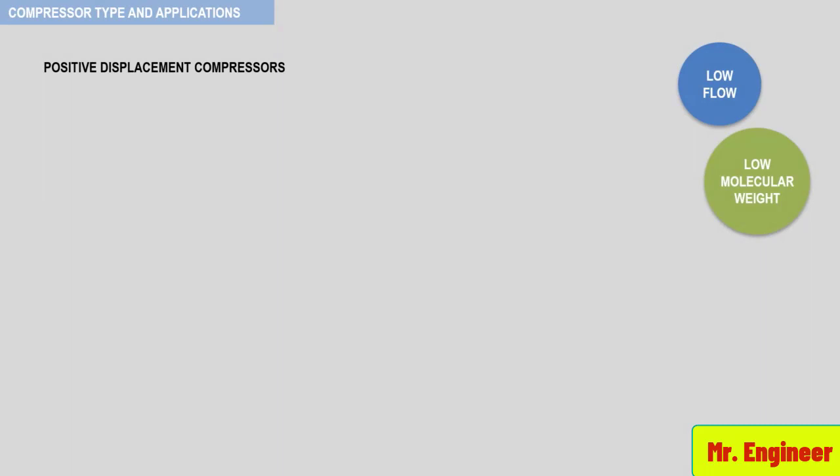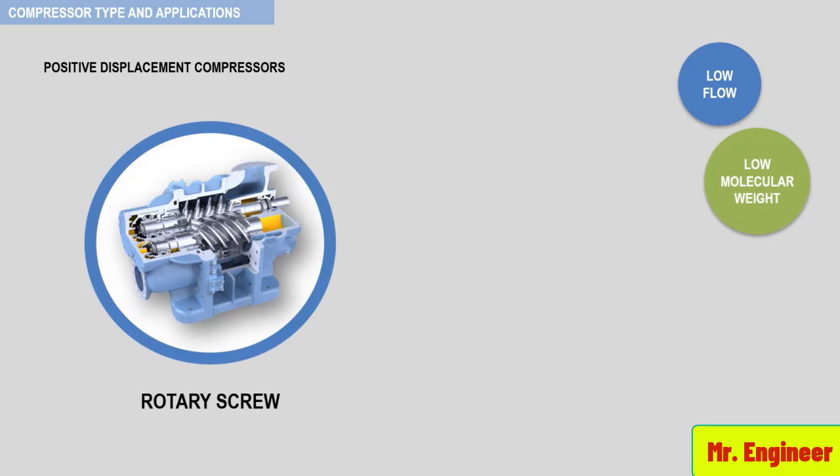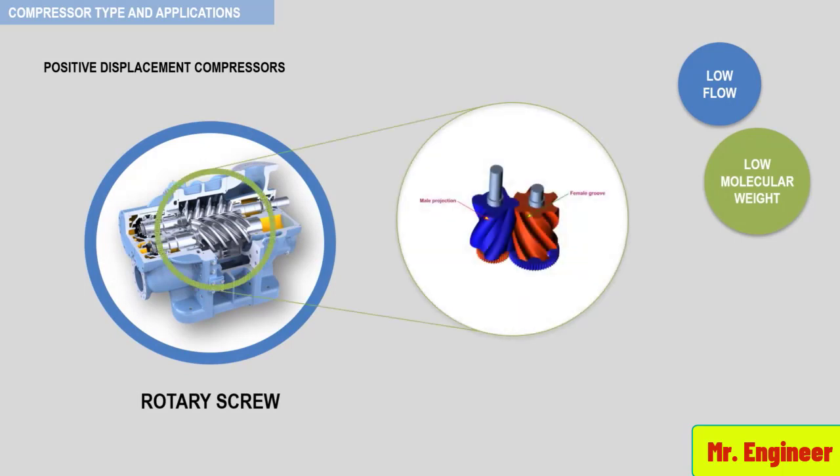The single-stage design of a rotary screw compressor depicted here consists of a pair of rotors that mesh in a one-piece dual-bore cylinder. The male rotor usually consists of four helical threads that are spaced 90 degrees apart. The female rotor usually consists of 6 helical grooves that are spaced 60 degrees apart. The rotor speed ratio is inversely proportional to the thread-groove ratio.